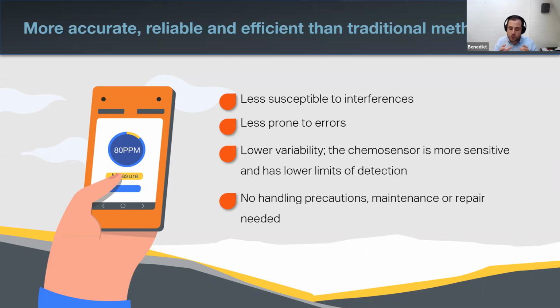On the other hand, we also try to make the whole system, also the device, as robust as possible. For example, our devices do not require any calibration. And how do we do that? For every cyanide measurement of a cartridge, there's a blank measurement done, which compensates for example for sensor drift. Hence it does not require calibration like an automated analyzer does. So there's nothing that you can screw up with a calibration, because you don't need a calibration.